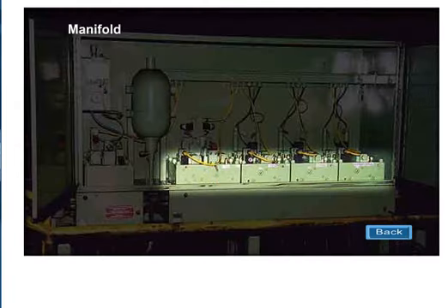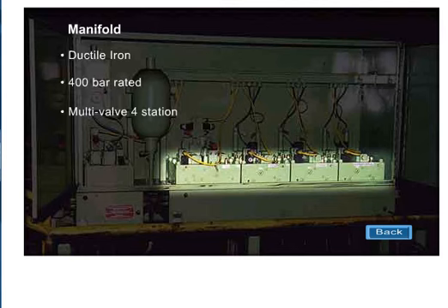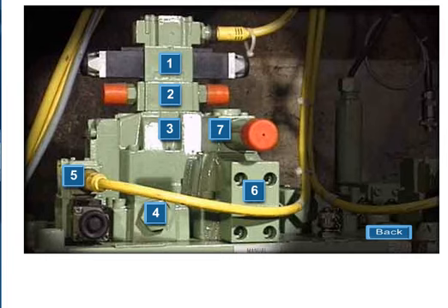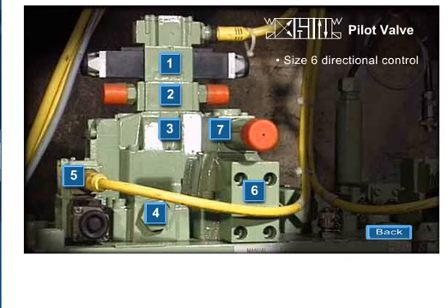Manifold assembly. Ductile iron. 400 bar rated. Multi-valve 4-station valve stack. Pilot valve, size 6 directional control valve. Float center. Shift size 25 directional control valve.